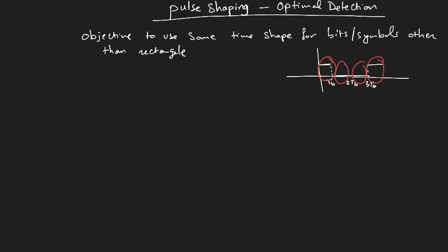It can be, by the way, 1 and the zeros are -1, right? So it doesn't always have to be ones and zeros. Most commonly in communication systems, it's +1s and -1s, okay? So the whole idea is that any pulse, any symbol, any bit, even if you are sending symbols, will have different magnitudes, but they will be transmitted as constant values during the duration of the symbol. So we call that rectangular pulse shape.